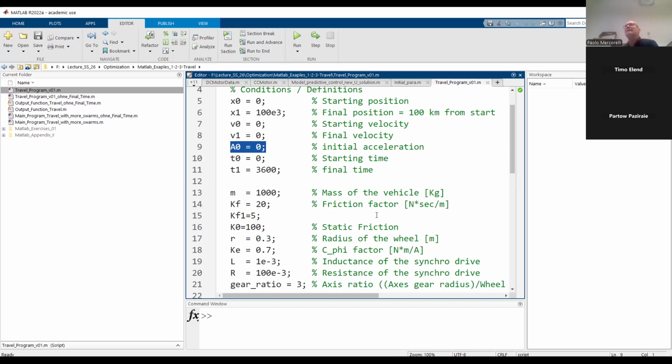Acceleration 0 at the beginning means I will start softly, without jerk effect. Moreover, if I include the final acceleration 0, again we have a softer landing. Of course, I need a polynomial of order 6 to satisfy all conditions and to optimize.